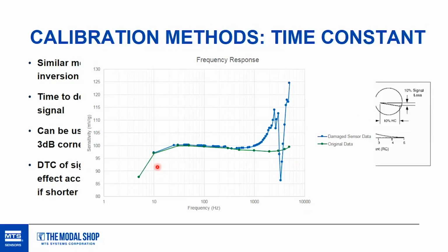So to reiterate, the most common way that we see sensors fail is up here at high frequency, that shift in the resonant frequency into your relevant test data. So if you're doing any one of these tests on a sensor, it's usually going to be the reference frequency, reference sensitivity test, and the very close second, or almost always second, test that people do is the frequency response in the high frequency regime. All these other tests that I've shown after this are additional tests that people do depending on the specific type of testing that they're doing. And I think that rounds it out for this section.